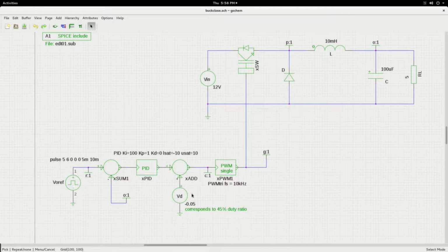So this is the nominal value, or the operating point value, which I am giving as a feed forward term, and this plus this will be the control voltage, and this is D plus D hat, with even the variation that is coming due to unwanted reasons and is coming from the controller. This goes into the PWM and controls the switch. So this is how we add this feed forward term here.